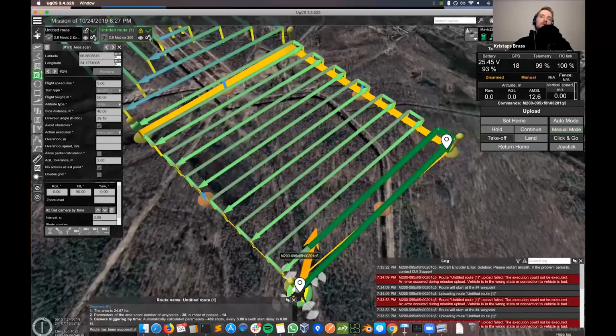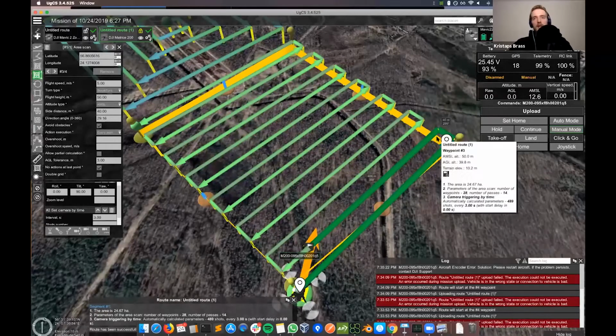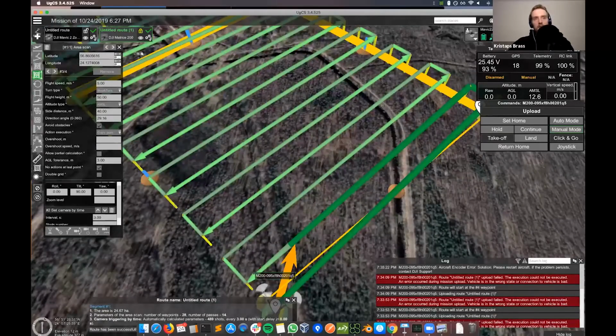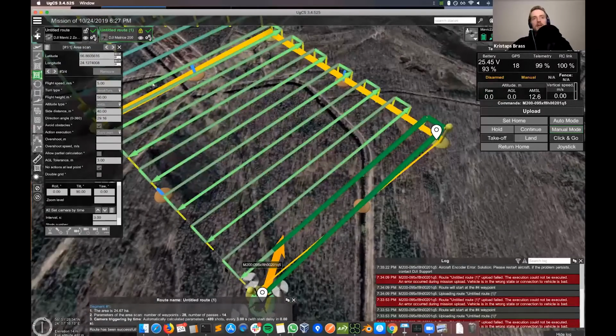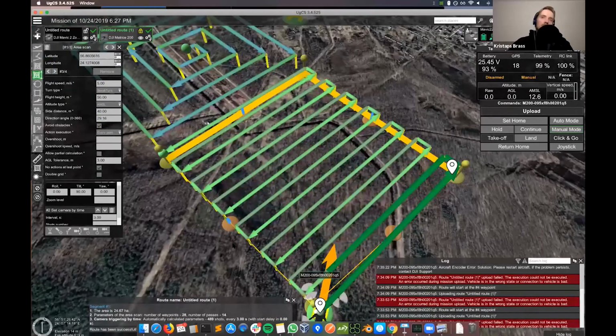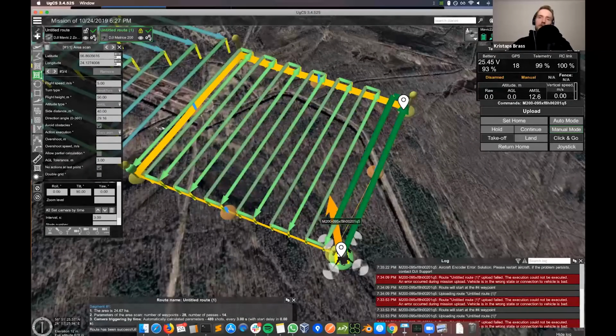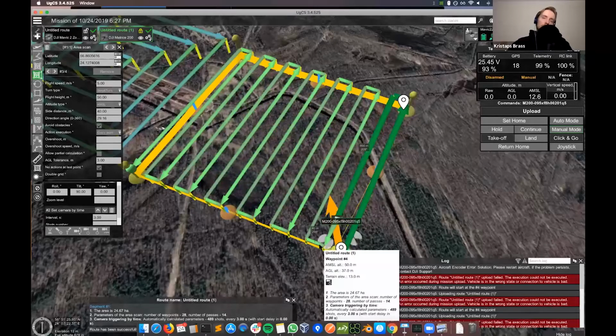About the whole search and rescue workflow. As I explained earlier, there's the video that the person is monitoring, and then the drone is taking photos. To speed up the search and rescue missions, you can use these place marks. But even if the drone goes until the end of the mission and it seems that you haven't found anything, what's also possible is that after the flight, once you land, you can download all the photos from the drone and look at them in more detail. You can also use them to create a map and import the map back.